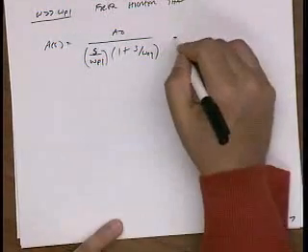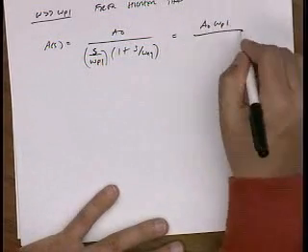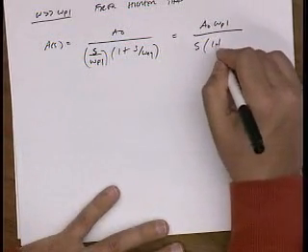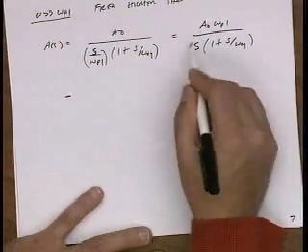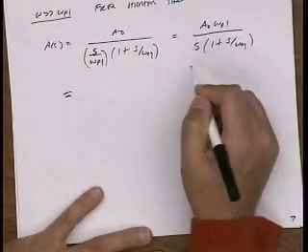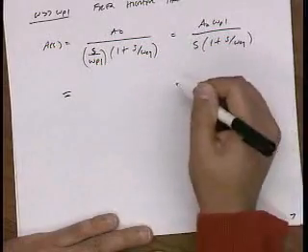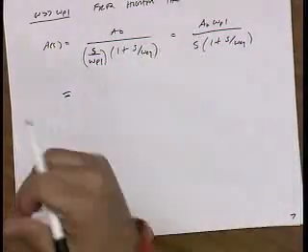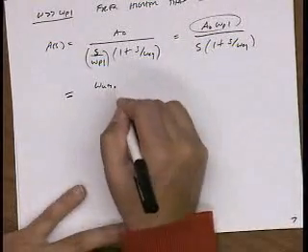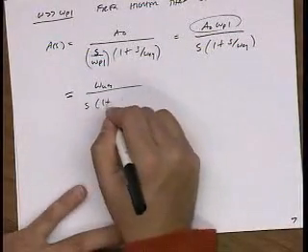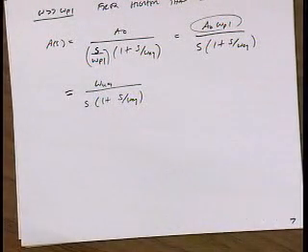And so I could write this as A naught omega P1 over s times 1 plus s over omega Q. And it looks like that first pole is just a DC pole. It's such a low frequency compared to what we're looking at that its contribution just looks like an integrator. We're getting a full 90 degrees phase shift from that pole. This, of course, I could write as omega UA, just like I did before. And so I simplify things a little bit here.